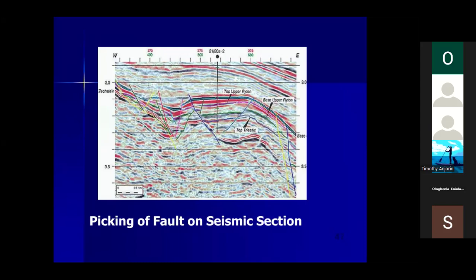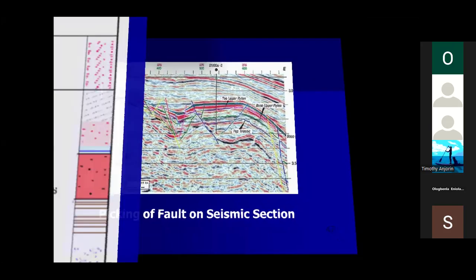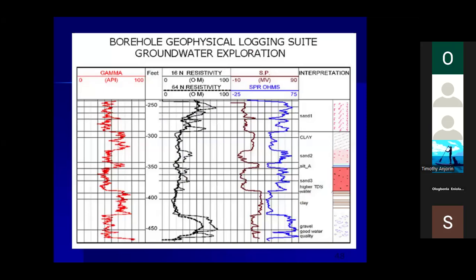We also talk about the borehole data. I told you that when you drill, you retrieve samples, and those samples can give us information. Likewise, there's an aspect of geophysics called borehole logging. After the hole has been drilled, certain measurements can also be taken along the borehole, and these measurements can also help us in our interpretation. Borehole logging is a detailed, continuous measurement along the borehole at every varying depth. So information is being digitized. We can measure along the borehole what the level of radioactivity is.